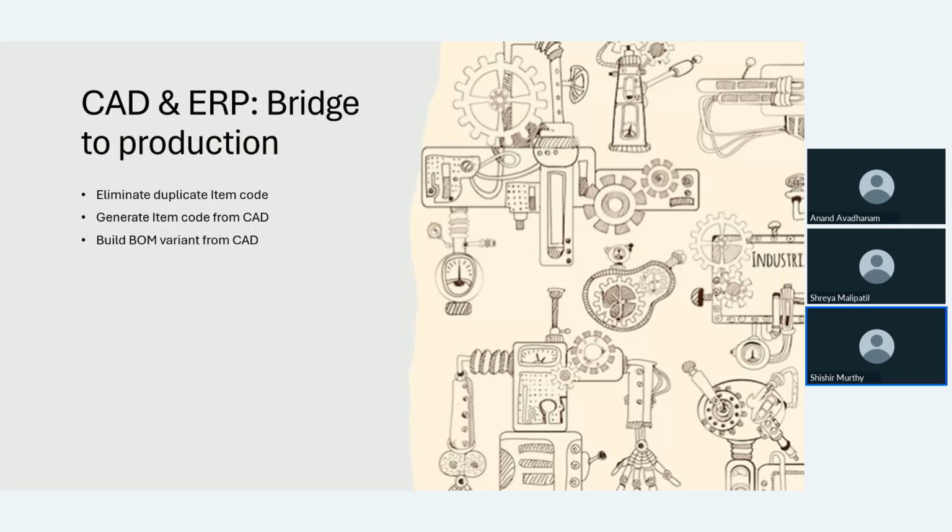And also to an extent ERP, depending on how you work, whether you are CAD first or item first approach. So if you're CAD first, you'll be creating the design, then you go to the ERP and create the item records and have all this BOM created. But if you're item first, then you would be creating item codes and probably have a pre bill of material. I would say it's a pseudo bill of material that's created with key components. Later, once design is done, you would update the whole overall completion of the form and then you go forward.